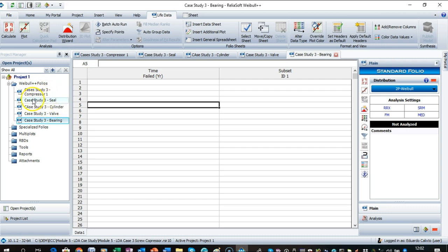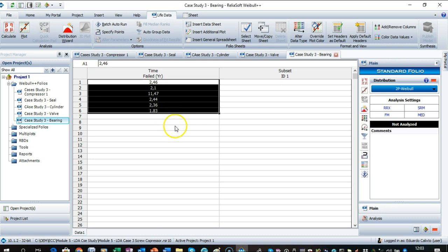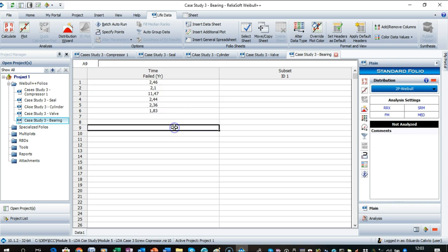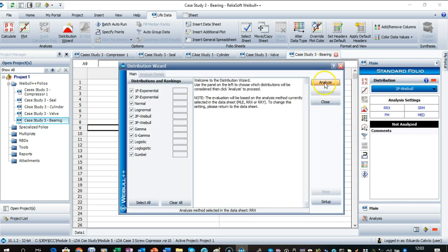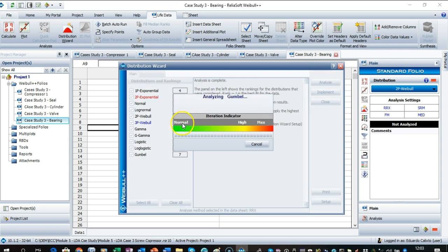In my maintenance strategy, I do not consider that you have a lognormal, or even if I use this database for a prediction, in a run analysis, I will not use that, and I need to be careful with that as well. So let's go to our goodness of fit test based on rank regression.